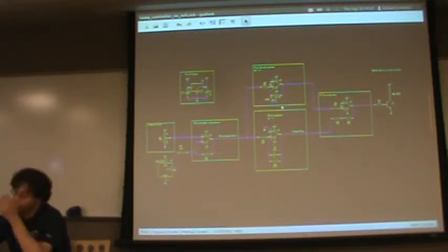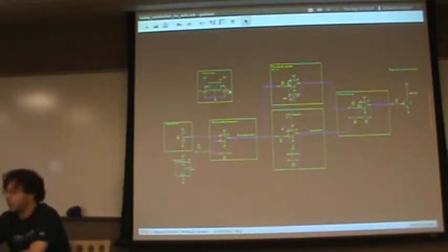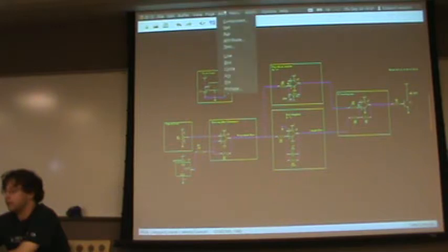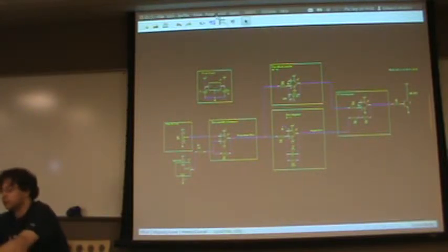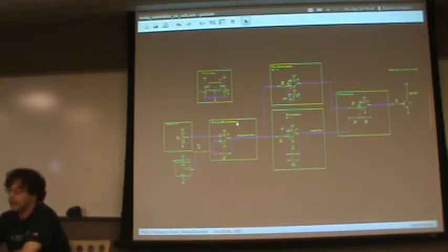But anyway, a few things I did here are probably good practice when you're making schematics. One thing is I like to actually indicate what things are on my schematic so people don't just have to squint at it, and also so I remember when I come back to it a year later. So I've got my power supply up here in a box. You can add all sorts of shapes. You can add boxes. You can add lines. Don't confuse lines and wires. Wires have a purpose. Lines are just pretty. You can put it in circles. So I boxed in all my stuff and I added text using the text tool to explain what everything is.